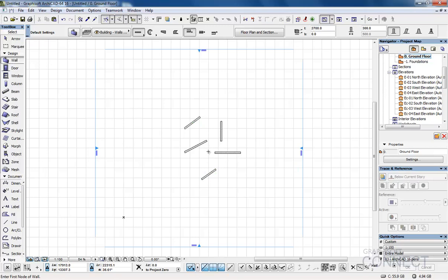So the easiest way to do this is, rather than switch back to the arrow tool to select, any time I hold the shift, you'll see as I press shift the cursor changes, so I now have an arrow. If I let go, it's back to just the drawing method, it's just a cross. So press and hold shift, put the mouse over an element, and you'll see as soon as I do that, it pre-selects in blue, tells me some information, it's a wall, what structure it is, etc. But if I click the mouse, it instantly turns green, which means I know it's actually selected.